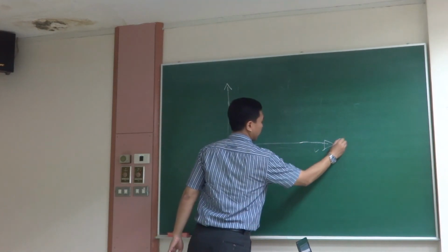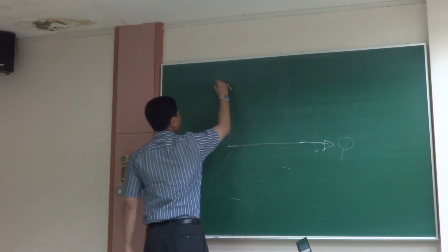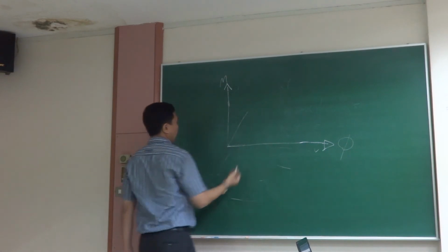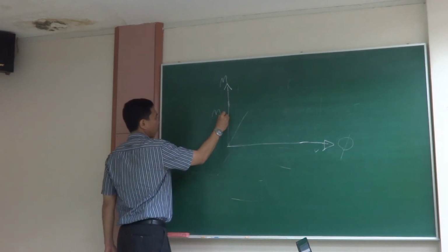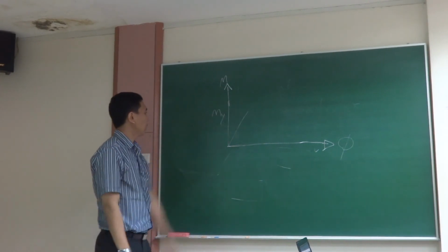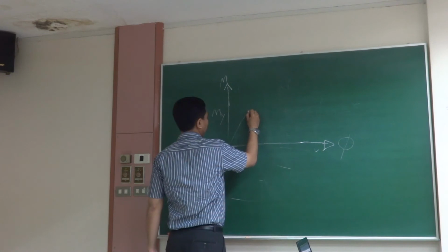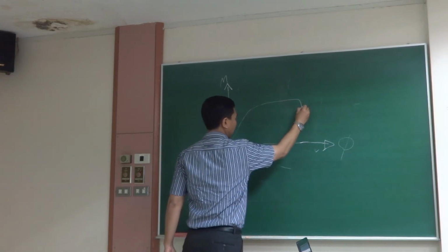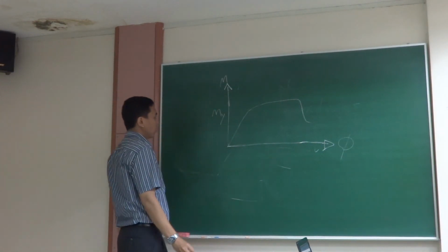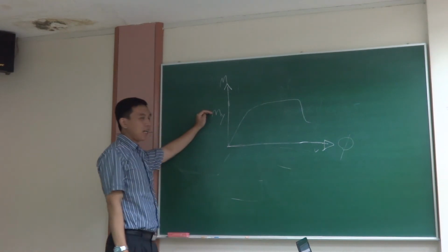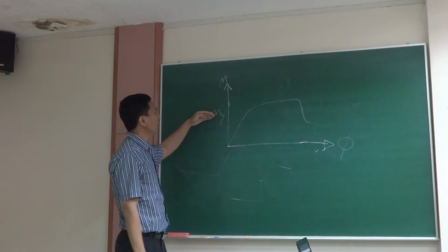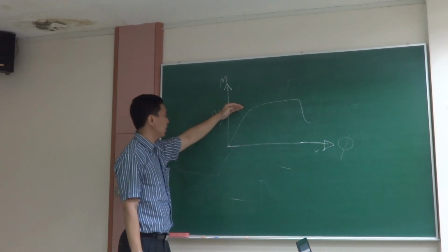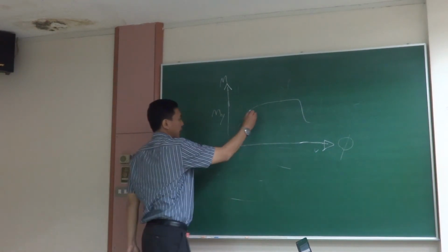This is the yielding moment. This is our design moment. Beyond that yielding moment, our beam will yield. Okay, and that's it. So under earthquake, we allow the yielding of the beams. The force in the beam will reach this MY, and the beam starts yielding.